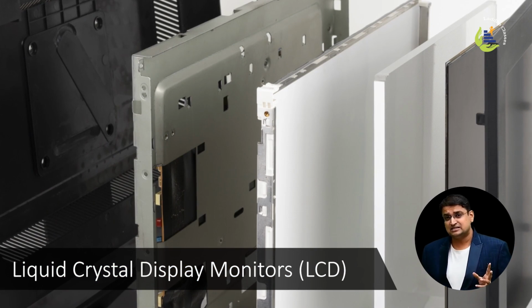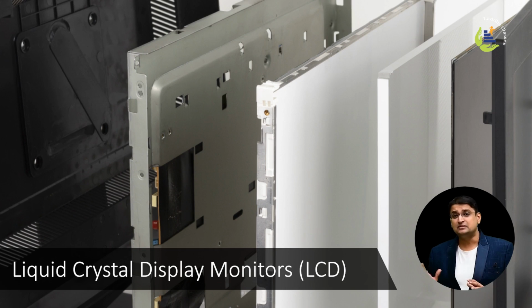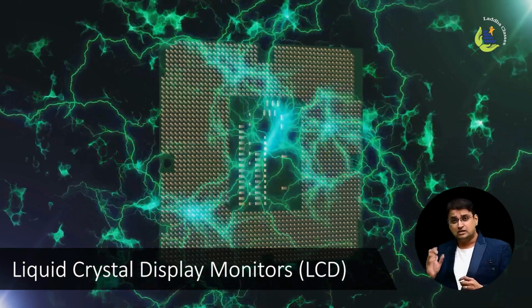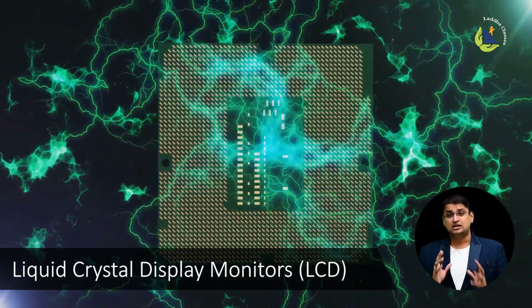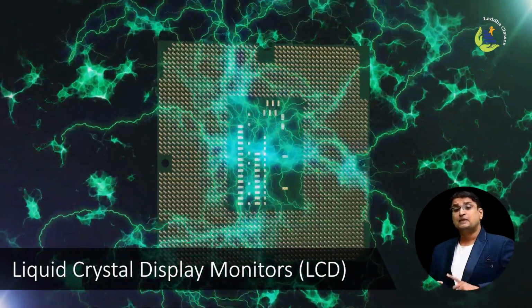These crystals are sandwiched between two layers of polarized panels with a light source, often a backlight, behind the screen to illuminate the display. The liquid crystals in the LCD screen can change their orientation in response to an electric current, altering the light passing through them to form individual pixels. The combination of colored filters and varying light levels creates the full spectrum of colors and the sharp images displayed on the screen.